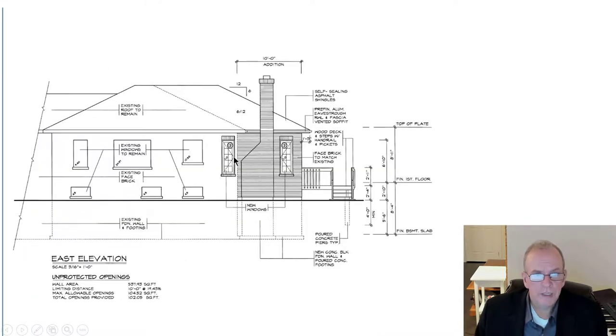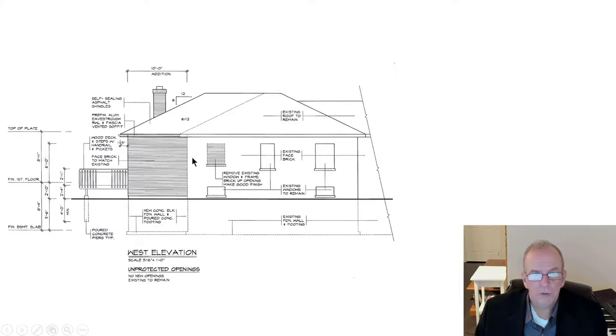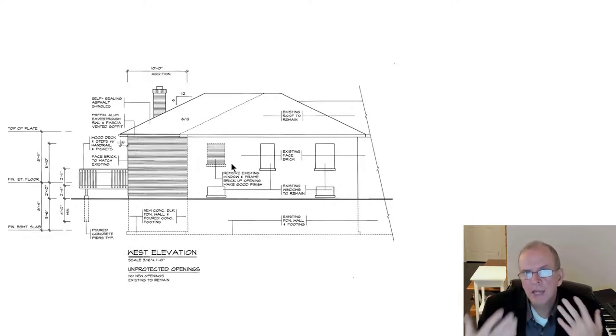I'm sure you've seen, well, if you haven't, you'll probably notice it after this lecture, older houses where they patched in a brick and they've done a horrible job and it just looks awful. And I'm sure you've seen ones that you probably haven't noticed because they just blend in. You can usually tell the mortar joints are a little bit different. We used to put a touch of black coloring in the mortar joint. And if it was a real matchup, I would even get some mud and rub it on and then clean it off. It makes it look a little bit more aged as opposed to too crisp and clean.